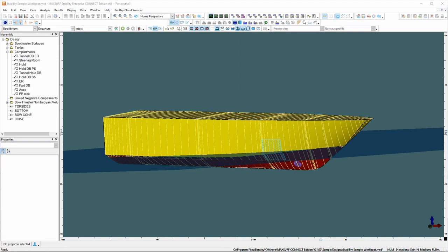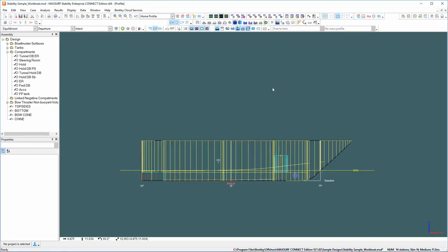The limiting kg analysis runs a series of large angle stability analyses, iterating to find the load case with the highest permissible VCG that passes all of the criteria. I really like a limiting kg analysis for early design, where you can define an immovable limit on how high that center of gravity can go without changes to the hull shape, or if you're limited by a damage case, without changes to your internal configuration.